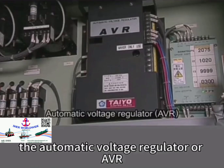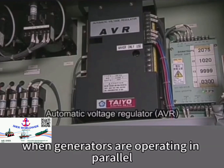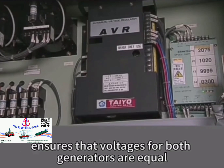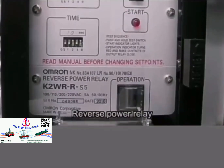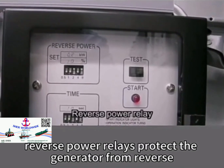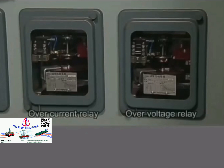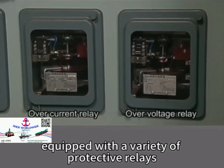The automatic voltage regulator, or AVR, regulates a generator's voltage. When generators are operating in parallel, the regulator ensures that voltages for both generators are equal. A type of protective relay, reverse power relays, protect the generator from reverse power. Switchboards are equipped with a variety of protective relays.